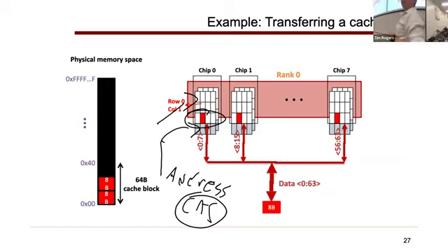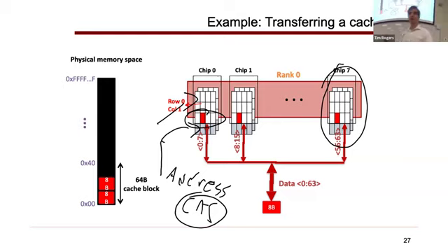Yeah. That's because of the limitation on the pin. And that's pin limit, right? So the internal parallelism of the memory chip is much larger. That's why sometimes PIM works. PIM is this thing called processing in memory. If you do digital processing in memory, the amount of throughput you have inside the memory chip is actually far greater than you have outside of it because you're pin limited. This is all inside one physical package, so I've got a lot more parallelism in here than I do once I go outside the package where I end up being pin limited. Good question. Other questions?